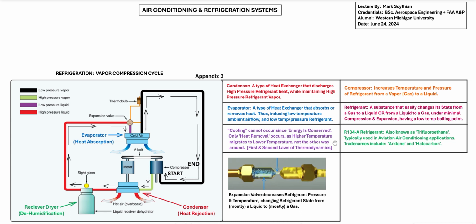Case in point, if we had a certain fuel or hydrocarbon and we compressed, vaporized it, ignited the fuel air charge, extracted thermal energy from that chemical potential energy, we then can induce a specific pressure spike onto a structure like a piston or turbine, thus converting it now into mechanical power. And so in this case, we are adding mechanical power to then induce pressure into the refrigerant to then ultimately remove heat. If we reverse this process, it would be similar to an internal combustion engine where we add heat in the form of fuel combustion to then induce mechanical power.